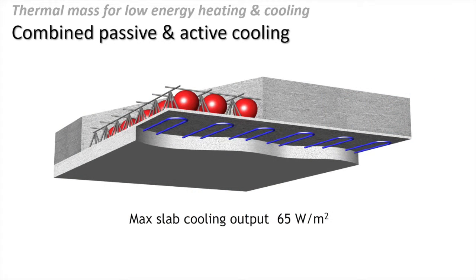And at the other end of the scale, we've got the kind of system we've just been hearing about at the White Collar Factory, where we've got embedded pipework linked sometimes to a borehole, bringing up water at about 13 degrees. There's a lot of that in London. That's an ideal temperature for this system. So that goes to the pipework, and it creates a soffit temperature generally of around 20 degrees, and that in turn will ensure that the environment in the building doesn't go above about 25, 26 degrees. And you can also link it to a heat pump to boost the temperature to provide radiant heating during the heating season. So it's a sort of year-round system.